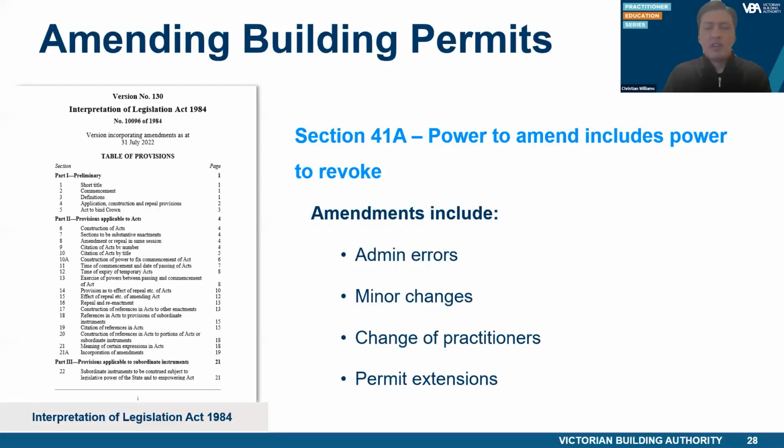The Act does not require the relevant building surveyor to recalculate the cost of the building work when amending a building permit. However, as per Section 205KA of the Act, if a revised cost of the building work exceeds $15,625, the applicant for the amendment must inform the VBA, and written notice must be provided within 28 days after becoming aware of the increase in costs. The RBS should make the applicant aware of their responsibility to notify the VBA when amending the building permit.